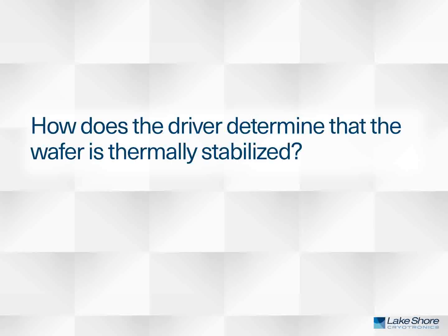The second thing we recommend, during kind of the development stage of your measurement, is going to temperature and then doing repeated device measurements. And so you want to make sure that your device measurements are consistent, and once that happens, you have equilibrium. So you can get a good feel for that equilibrium time for one device, and then kind of apply it to a larger sampling of devices.